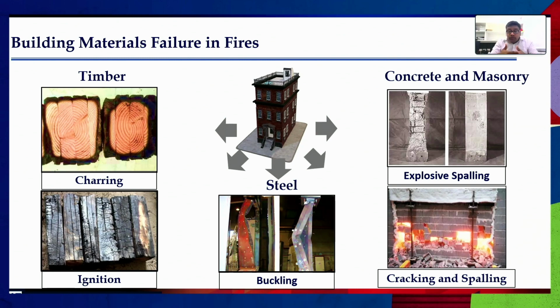So if you protect that with proper overlapping, the splice, and the lap joints, it will safeguard the building. And concrete could spall or crack, and similarly masonry materials could do that too.